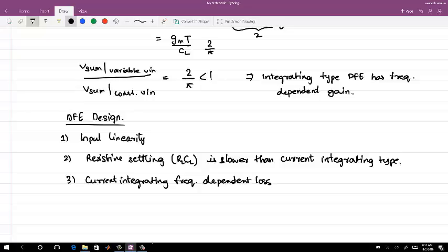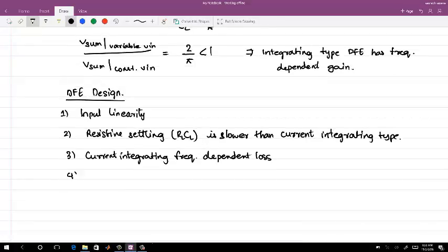And the last one is, none of these techniques is doing anything to the first loop. You're not reducing any timing for the first loop which we are closing, right? The first loop still has to close, from the comparator to the output, whether you integrate for that bit period or you settle it with RLCL, and the setup time for the comparator has been untouched. So we are not gaining anything with these two techniques here. Okay, so closing the first tap is most critical.